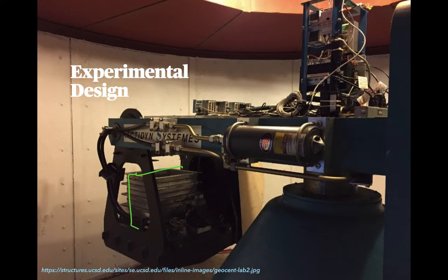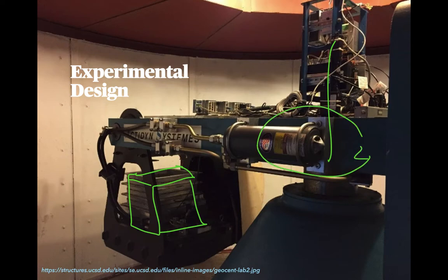And the cool thing about centrifuges in geotechnics and structural engineering is that if you spin this guy around fast enough, this centrifuge here, this rotates, it'll actually generate enough centripetal force inside this bucket that the bucket contents, if it's filled with soil and some kind of miniaturized anchor, will start acting like an anchor that's many times larger at the bottom of the ocean and has several tons of weight above it.